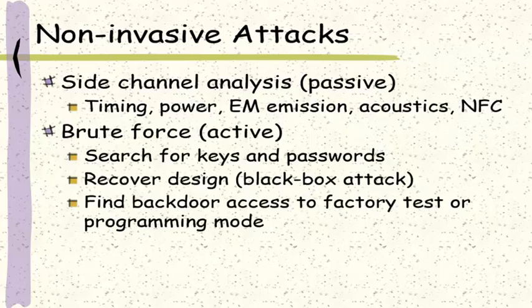Brute force attack is a strategy for searching information on the chip. It is normally an organized search instead of a random search. For example, attackers can search for secret keys and passwords if they are not sufficiently long, or if their memory addresses can be predicted or are restricted to certain areas. They can also try to rebuild the truth table of input-output pairs to reveal the functionality of the design. Of course, this will be limited to relatively small designs.